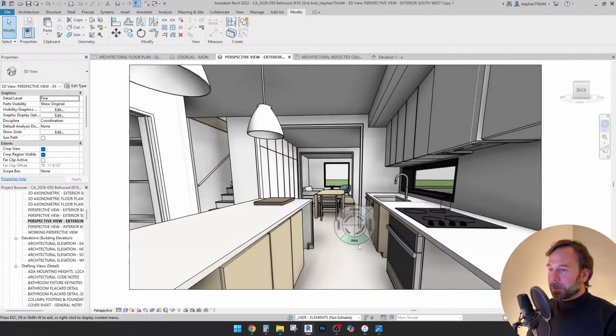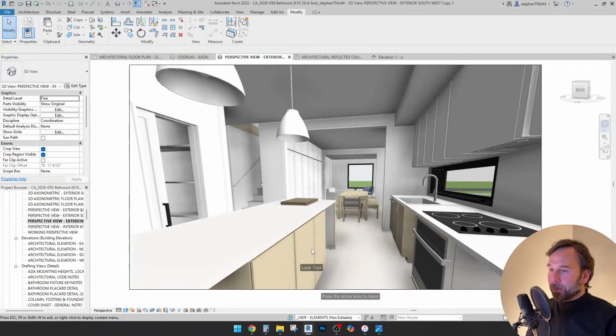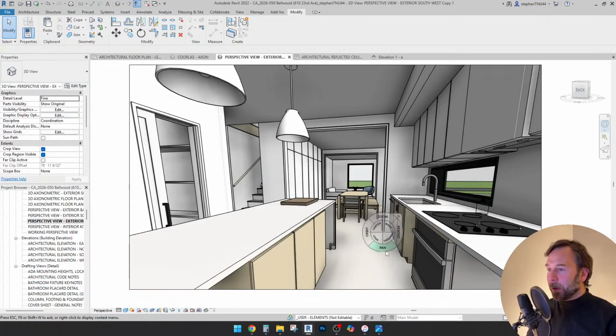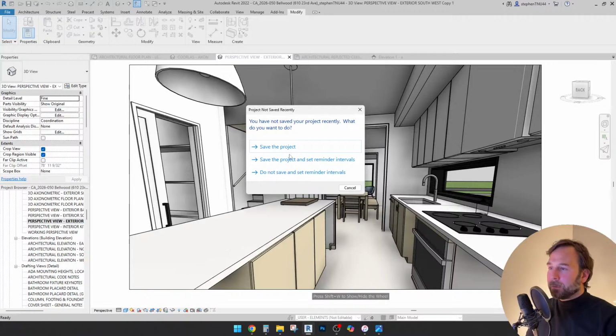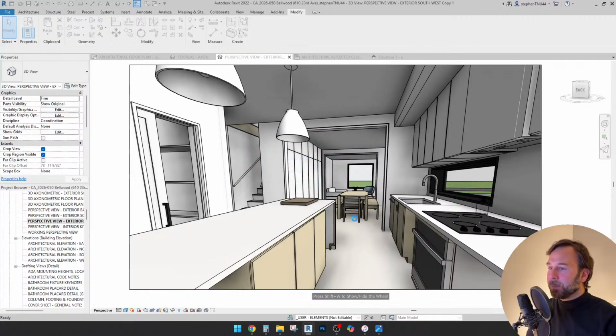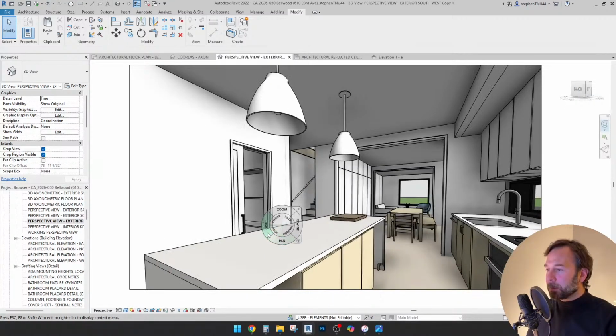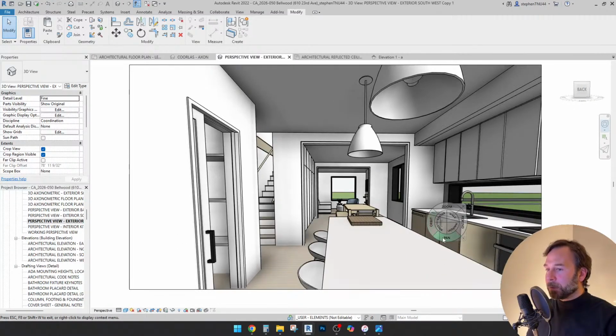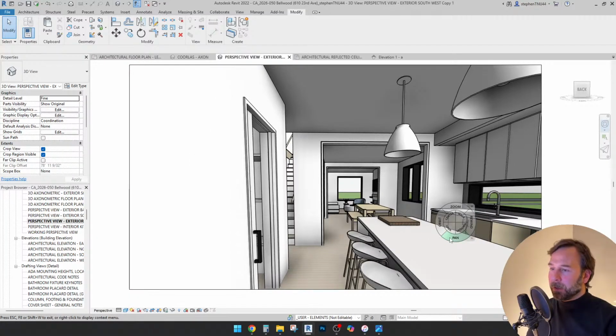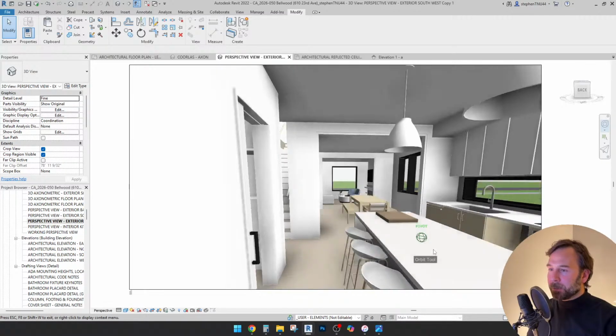So we had a 3'6" walk aisle here, which is great. You're going to be able to pull down your door and have a few extra inches to navigate around. You really shouldn't be doing that all too often, so I think it's appropriate for the oven to be located behind this area. We have the dishwasher outside of that area, so you're not having too many doors located within this aisle width. So I'm happy with that. I think that works. And then this, we increased a few extra inches on this side just because if people are sitting here or pulled out, you want a little extra walking space behind these.